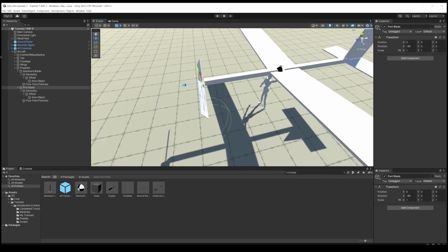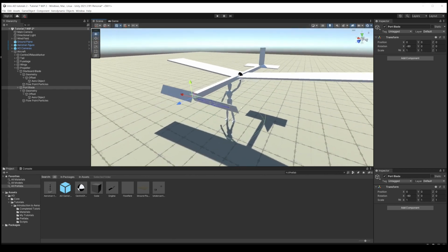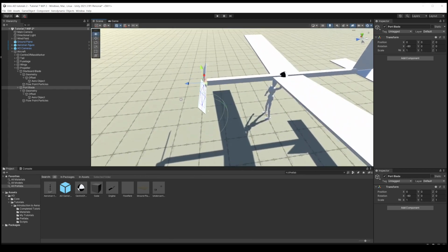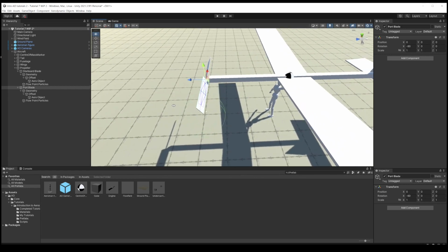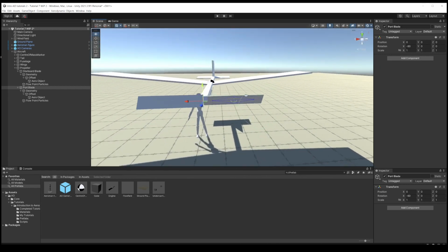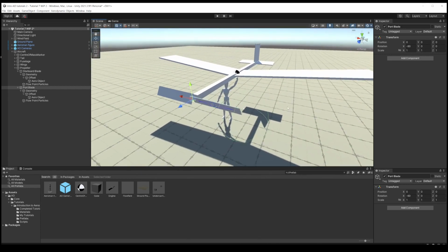And when this plane's going fast, you may find that actually the propeller's producing negative thrust if the pitch angle isn't high enough. Anyway, this will be fine for us for now. Okay, once again, just because it's fun, let's just spin the propeller, and it's actually going to be spinning clockwise as the man sees it, so that's right, so that's going to be generating lift on those blades.